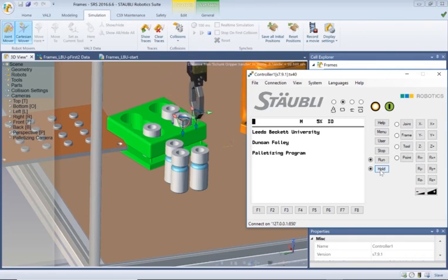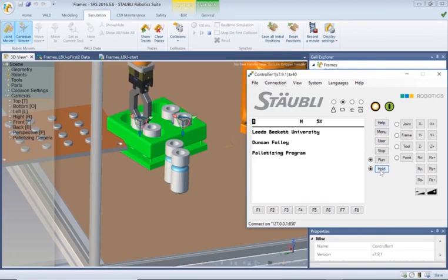Once we did that, we put the code in, which has two main parts: the main body of the text that does the palletizing as such, and then the set frames. In the main body, lines 19 and 20 that ran the set frames, we only really have to do that once. Then we defined the main points, and the XY coordinates of the pallet and the bottles.